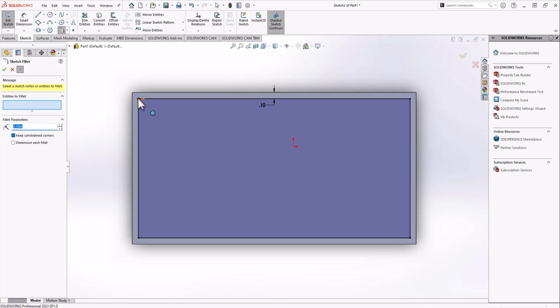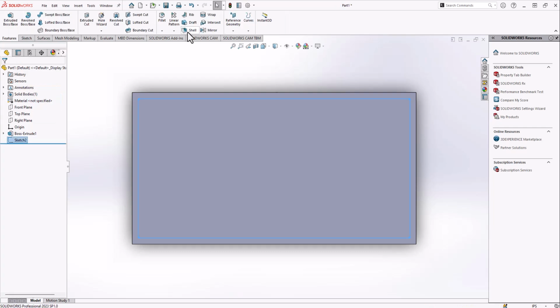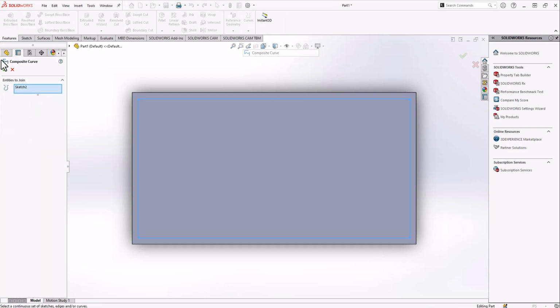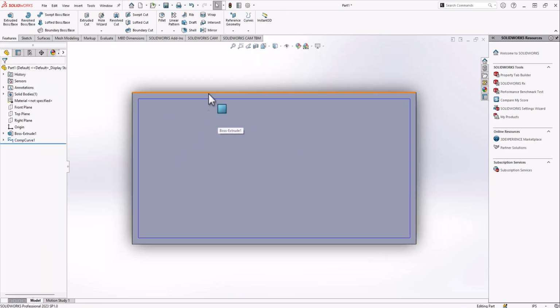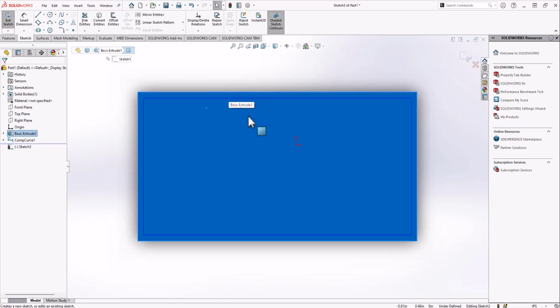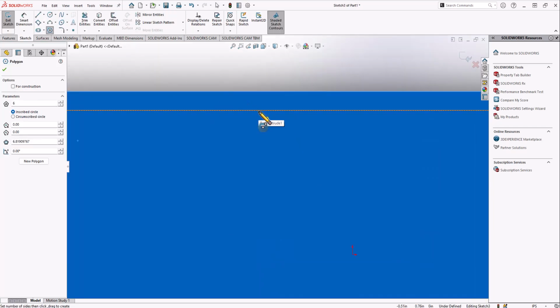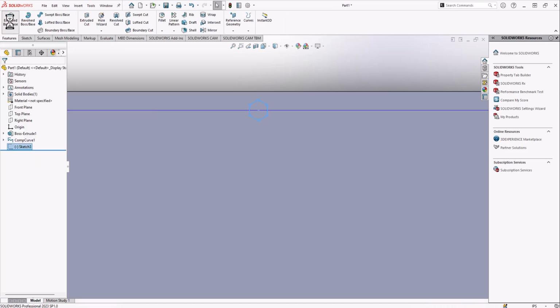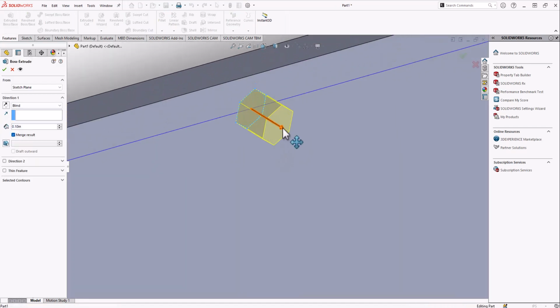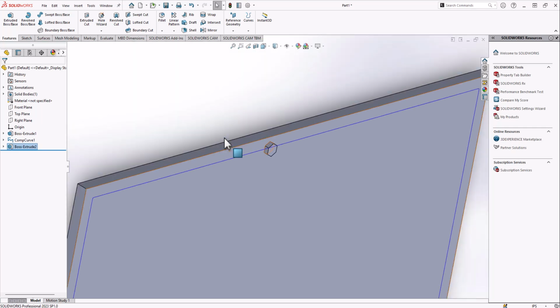So I'm just going to do a really tiny fillet on each of the edges just to make the curve continuous. When I do that, then I'm going to go to curves, composite curve, and that will be a guide curve now essentially. So then I can go and make my bolt or what have you. This works for patterning really anything.